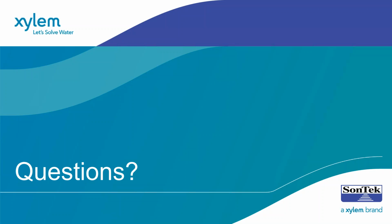Sure. But I think there are also some important features with the Pulsed Doppler IQ, specifically your Smart QC feature. That instrument is going to tell you what sort of condition you're running into. If one of the beams is blocked, multiple beams are blocked, you have debris or damage, low power, whatever you might be experiencing, the instrument will log that error and either report it through some sort of real-time system or log it internally for review later on.